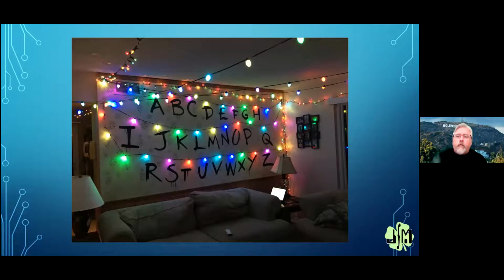It has one Propeller 1 and then a whole bunch of little DMX bricks placed throughout the project. The Propeller knows each of the sections on the display and does the animation. In fact, I have 5 animation cogs running simultaneously. Each of those animations feed their data directly into the DMX stream, which is running in its own cog, and it goes out. So we have the ability to do this very complex animation.